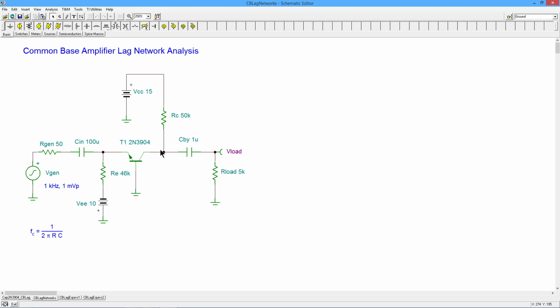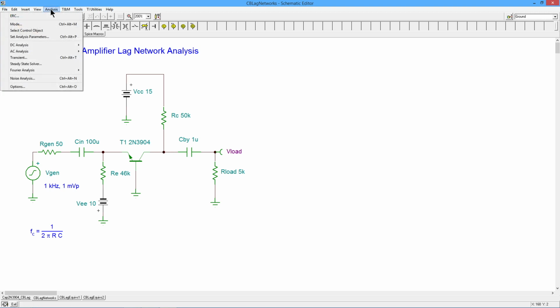Now we're going to need that in a little bit. You're going to see why. But before we go any further, the R prime e on this is always the constant 26 millivolts divided by the emitter current. So 26 millivolts divided by this slightly more than 0.2 mils will get us 129 ohms. All right. Okie doke. So let's go up and do a little DC analysis.